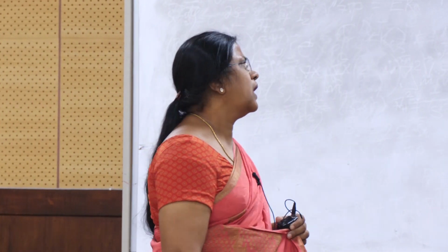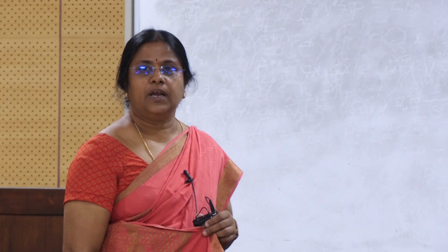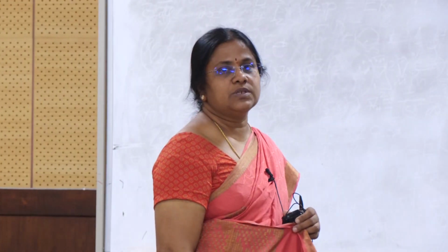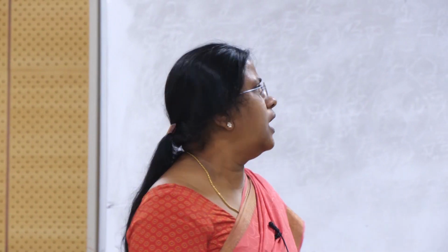Here for the velocity vector we have two components. Let us derive that also. The next one is the Navier-Stokes equation. Ra is the Rayleigh number and Pr is the Prandtl number. That is equation number 1.2. On the left hand side, the first term is the unsteady term and on the right hand side the first term is the nonlinear term, then the pressure, and next the temperature.